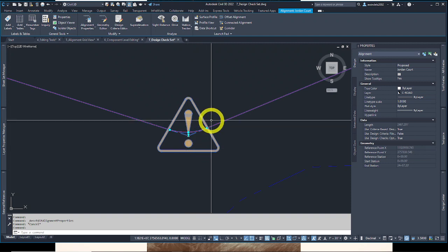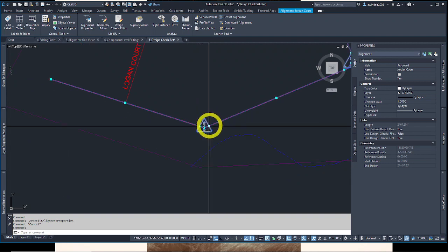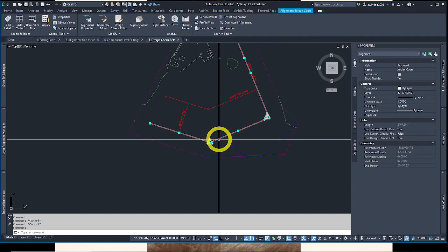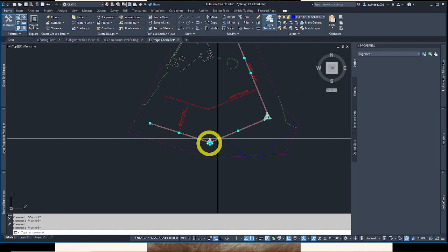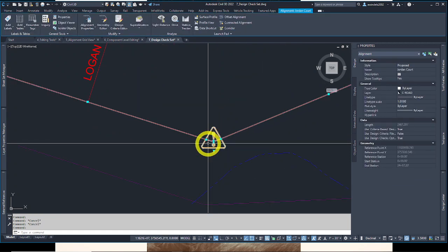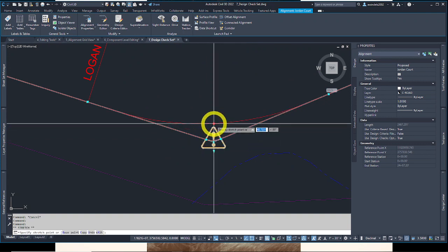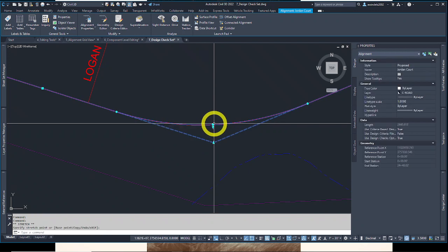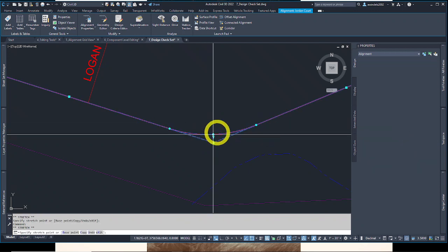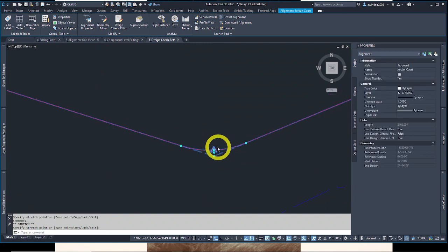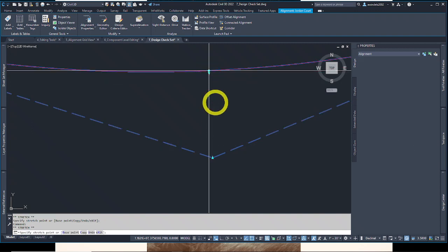We'll click on the alignment to display its grips, which we have done. Let's zoom out a little bit and re-click so the grips are a little more spaced out. One more time. And let's click this one circular to the north a little bit. And we're just going to kind of repeat until the shield disappears. And it did in the first attempt. So if we go back, it's still gone. The tighter this curve is, I'm guessing it's a minimum radius violation. So we'll move that back up.